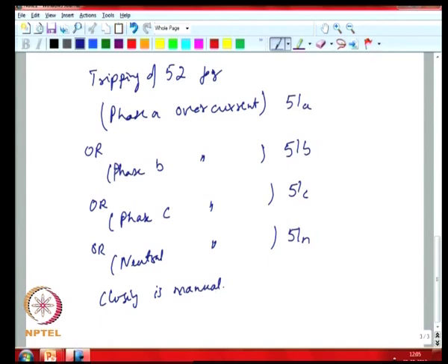And we saw when we were discussing circuit breaker protection, you could now have multiple, say, inverse time characteristics. So, to have short, long, instantaneous. So, essentially you are now grouping together multiple such functionalities to implement such functions.